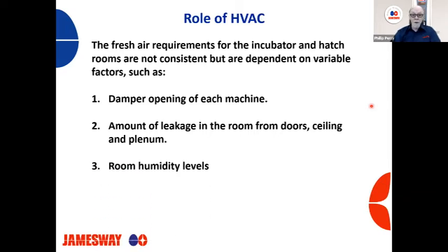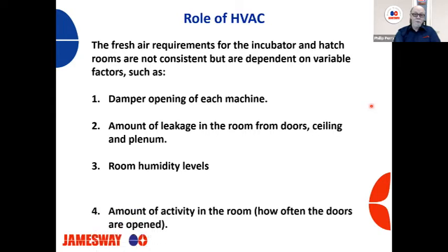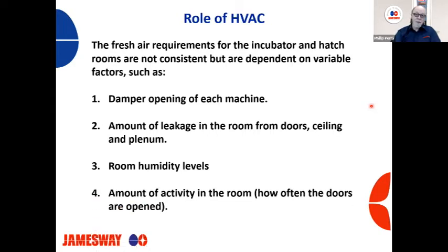The room humidity levels, again, affect the operation of the machine. If you're in a cool climate, let's make sure we get some humidifiers to keep a constant level of 55 to 60% relative humidity in those rooms. The amount of activity in the room, how often doors are open.